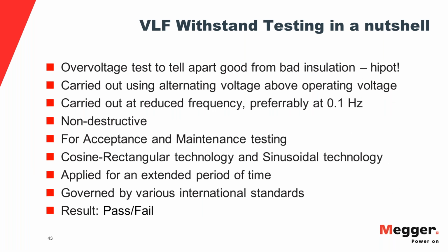So just to summarize, VLF withstand testing in a nutshell: it's an overvoltage test, like a hipot, to test for good insulation. You carry it out with AC, preferably, or strongly preferably, at 0.1 hertz. It is a non-destructive test. You can use it for acceptance tests and maintenance testing, to ensure, especially during acceptance tests, the operational integrity.